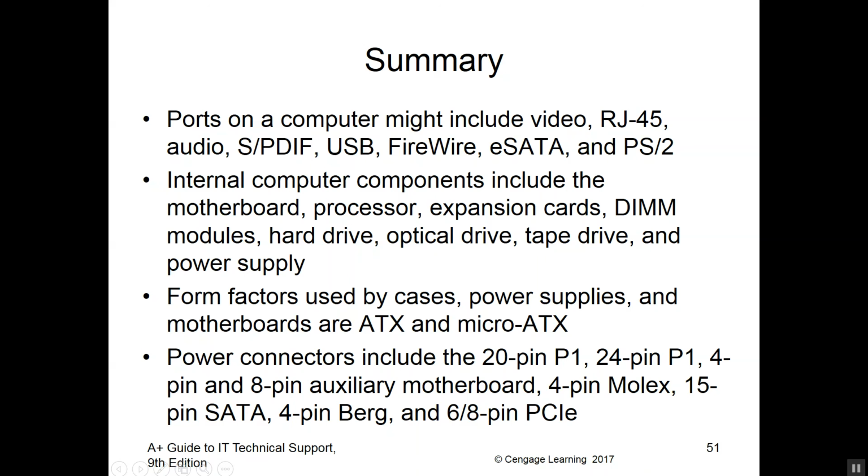Power connectors include 20-pin, which is a P1, 24-pin P1, 4-pin and 8-pin auxiliary motherboard, 4-pin Molex, that's the most common connection you'll see, or the 15-pin SATA. You need to recognize every one of these pins by sight and know what they are and distinguish them from any of the others. Okay?